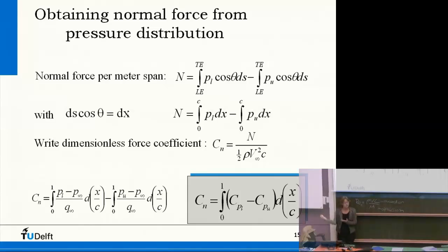The flow we see is completely different from what is outside, or might completely be different. Namely, transition point, separation, all these viscous dominated effects will be wrong if you have the wrong Reynolds number. So it's very important to have the similar Reynolds number and the similar Mach number. Then your flow behaves the same.